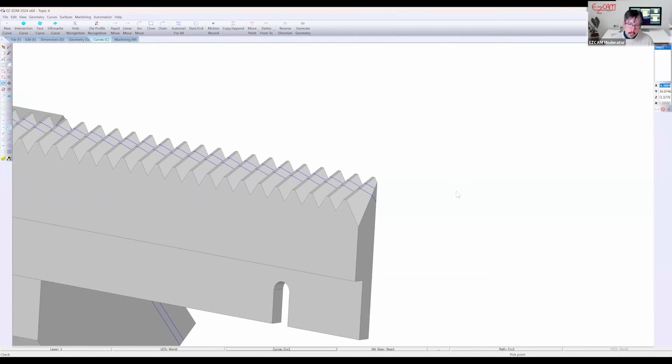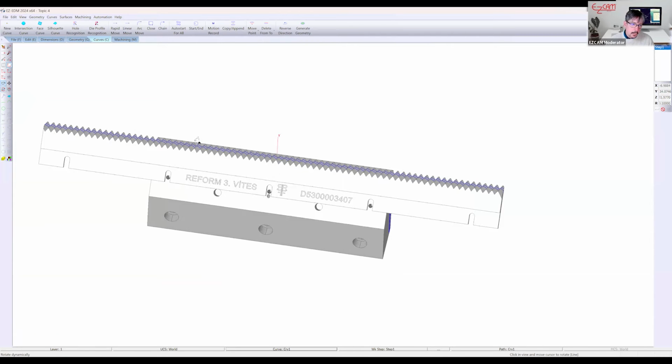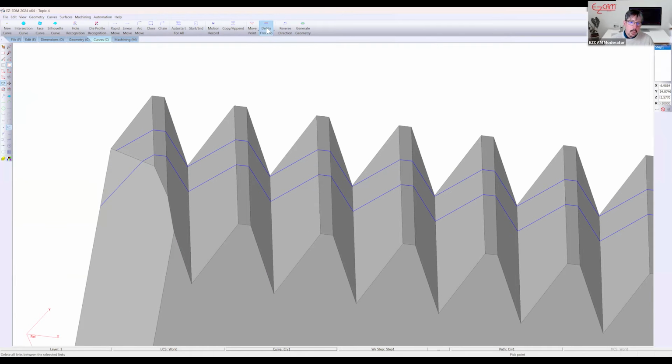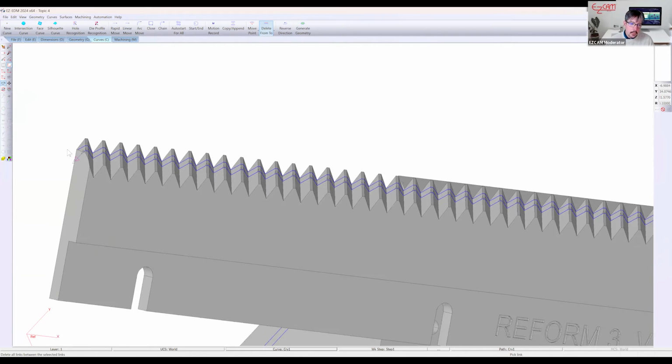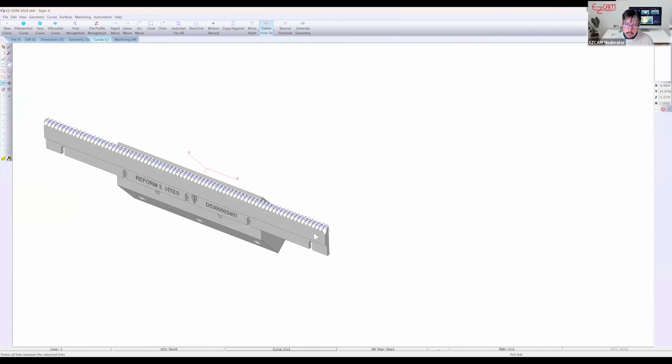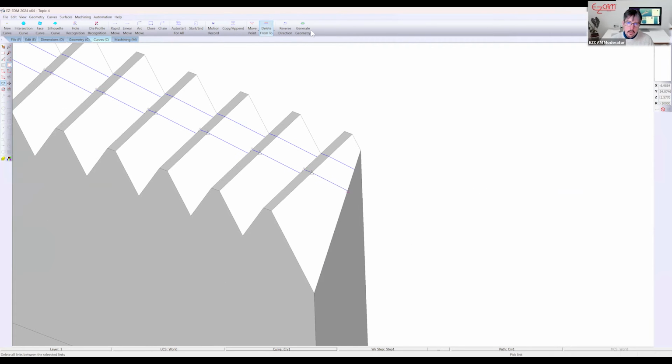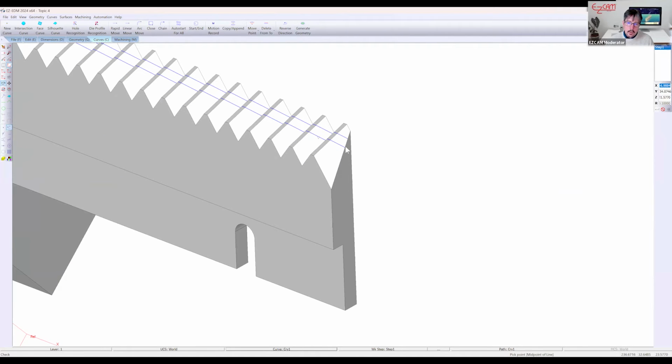And our curve is uniform. It starts down this area here. I'm going to do the delete from and to. From this point over to this point. Generate our geometry. Because what I'm going to do is give it a lead in and lead out, and I don't want to stop here. It's not going to give us a complete toolpath.